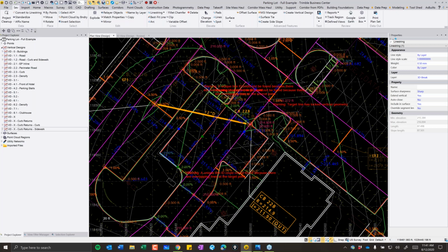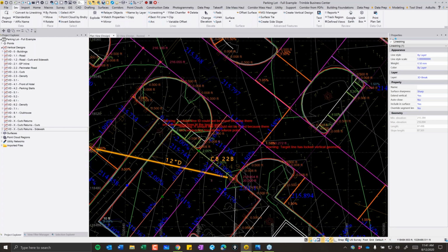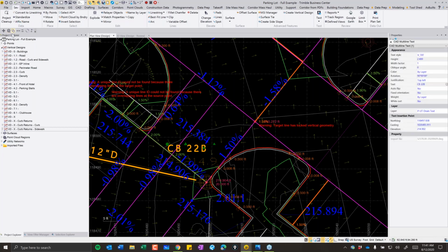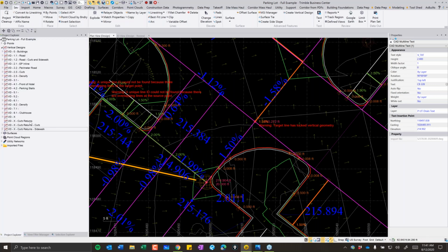That's how the engineer planned it. That's how I'm going to have to do it. And the areas around those curved corner islands, the quadrant corners, are warped in from the elevations you're given on the curb or the flow line, and also the elevations computed by the vertical design along those magenta lines. So you basically warp those together to make them fit, but they're designed from a few elevations and a few slopes to get to where you want to be.